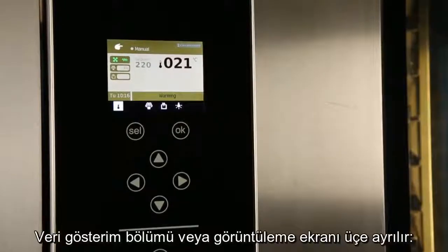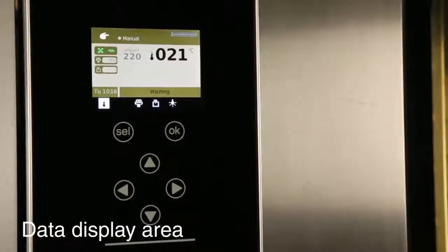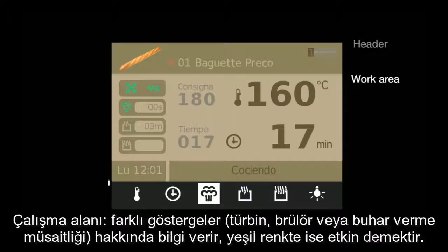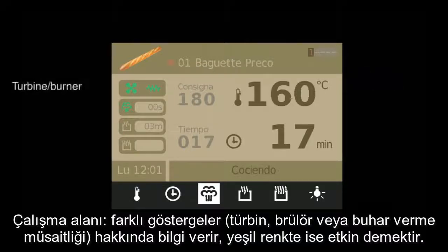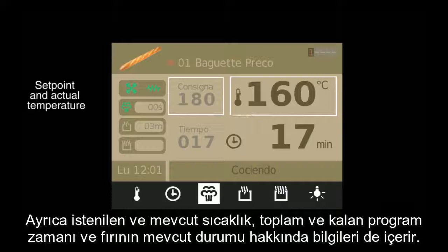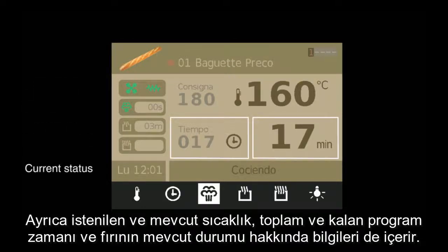The Data Display Area, or display screen, is divided into 3 areas. Header shows information about the selected program, such as the image or its current phase. Work Area shows information about the different indicators, turbine, burner or steam permittivity, which will be green when activated, as well as the set point and actual temperature, total and remaining program time and current status of the oven.